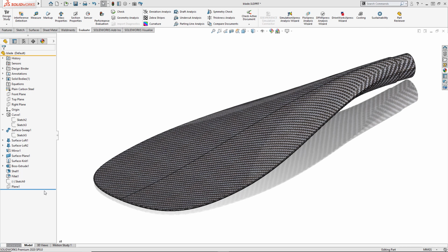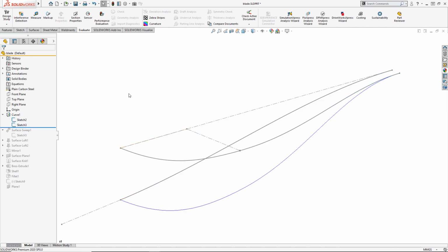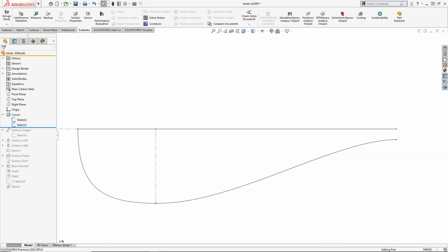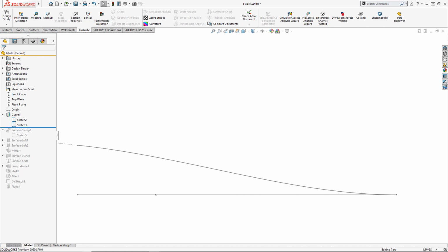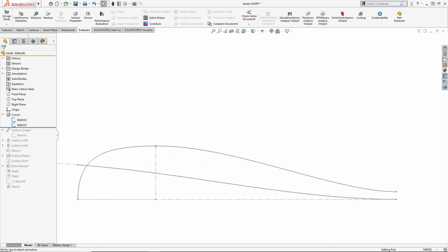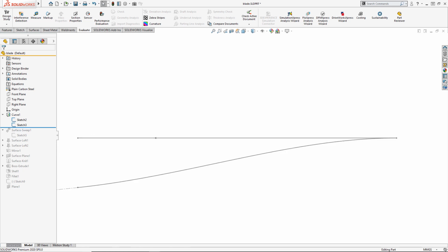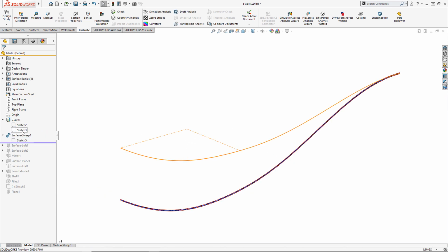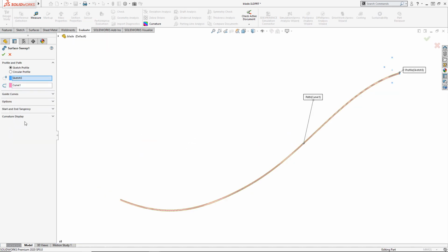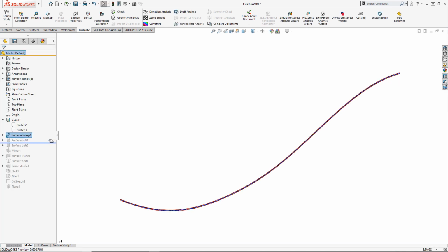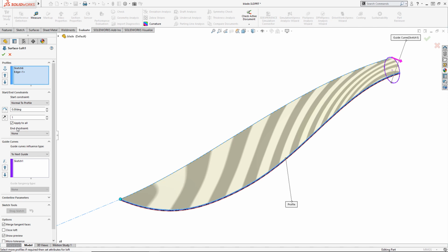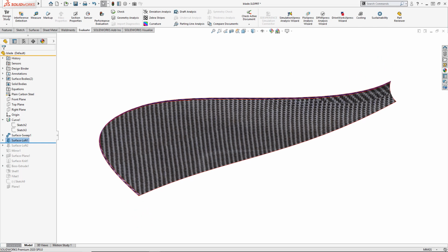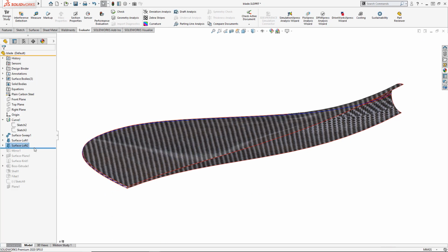Instead, we can create separate points of reference and then slowly patch together our final design. We've used guide curves again, but we have merged multiple guide curves to create a single composite curve that defines the external leading edge of this blade. With the external boundary created, we can construct the rest of the model by patching in the remaining surfaces. Typically, this is from lofting from a new sketch drawn on the centre line of the paddle to the newly created edge running around the outside of the blade. This needs to be repeated underneath, of course.